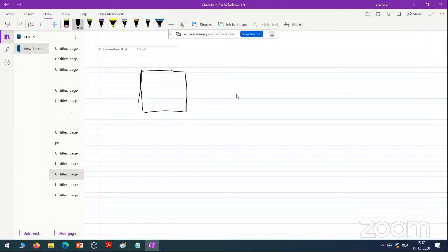If this is A, B, C, D, then this becomes A dash, B dash, C dash, and D dash. Suppose this is D dash. If this angle is alpha, this is beta, and this is alpha, then when we write gamma xy, this is essentially alpha plus beta. This is engineering strain.